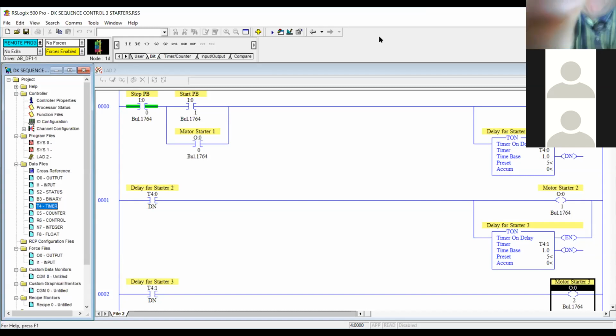The whole purpose of the center position, REM remote, is so that you can actually flip the switch from the laptop. You can toggle from program to run from the laptop if you leave it in the center position in remote. It actually causes the switch to be a remote controlled switch. That's what it does. Does that make sense? Yes, sir. So that's pretty easy to remember.